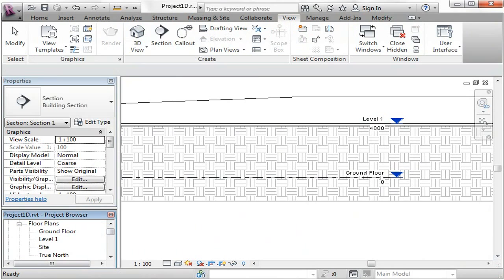Now when we created our building pad, even though we were in the site level, we were able to specify the level 1 as the level we want our building pad on. Now as you create your building model, you will need to establish levels very early on, and we will be doing that in the first tutorial of set 2.